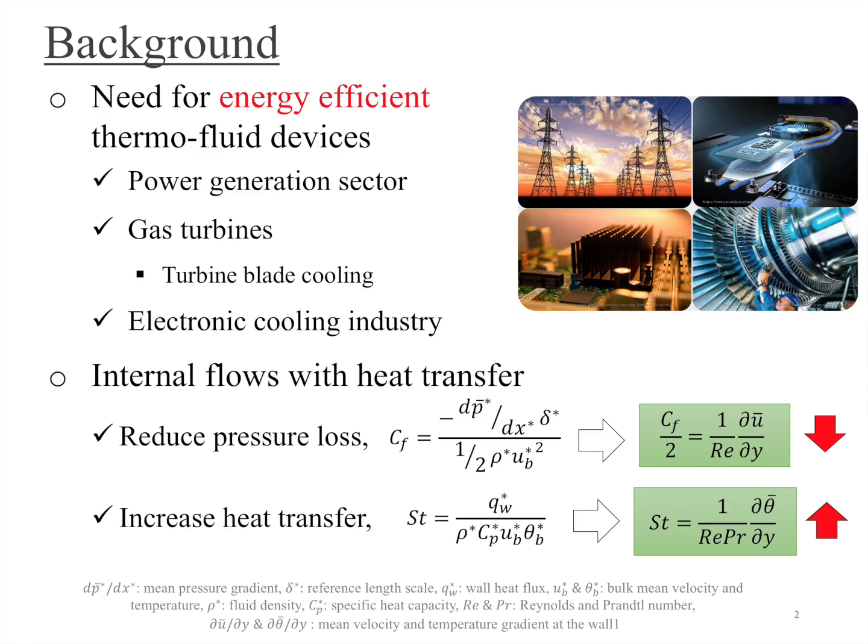There is a never-ending demand for improving the energy efficiency of thermofluid devices like heat exchangers, owing to its wide range of industrial applications. Now, for improving the energy efficiency of such a system, we need to aim at reducing the pressure loss and increasing the heat transfer. And they are respectively quantified using the non-dimensional parameters, the skin friction coefficient, and the Stanton number St. Thus, enhancing heat transfer while minimizing the pressure loss penalty is one of the ultimate goals in heat transfer research.